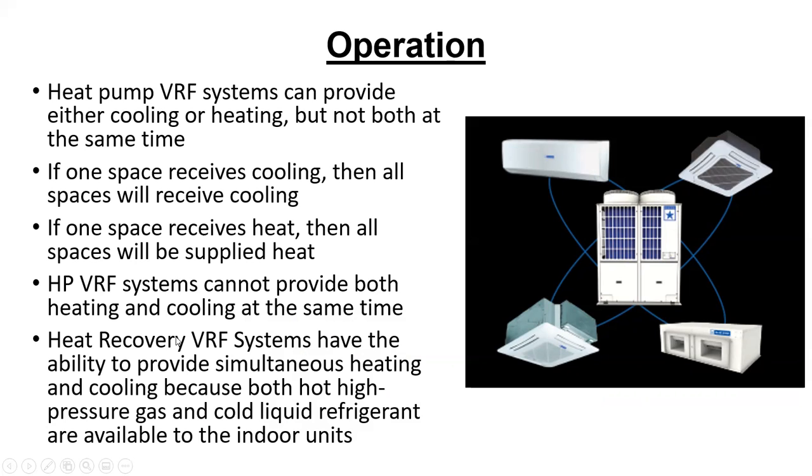That sounds inconvenient. Because, what if you're conditioning 6 offices with a VRF heat pump system, and you get 2 people that want air conditioning and 4 people that want heat? Guess what? Somebody's going to be unhappy because it's either heating or it's air conditioning. So if one space receives cooling, then all spaces will receive cooling. If one space receives heat, then all spaces will be supplied heat. Heat pump VRF systems cannot provide both heat and cooling at the same time.